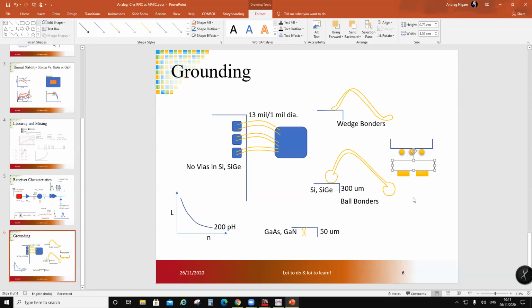So earlier in my career, in 2000, I started, and by the end of 2000 I was doing flip chips. These flip chips have a problem: the PA would start floating, because I was taking about 2 watts of power out of a GSM PA. So these practical problems are there with silicon germanium. Flip chip is one technology.